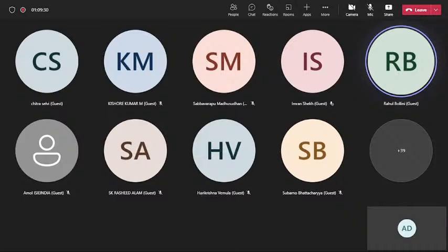Basically, they put it in a shredder kind of thing where all the metals come out. There's aluminum granules that come out, copper granules come out, and then there is a black mass that comes out. And the cell can, which is cylindrical SS304, also comes out separately. And then the plastic separator comes out. But the main value is for the black mass.